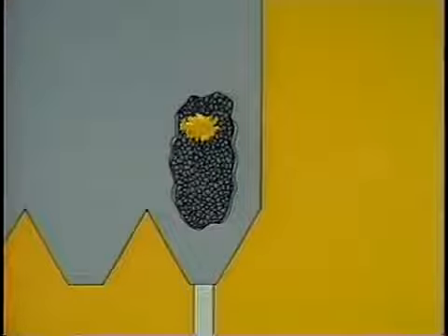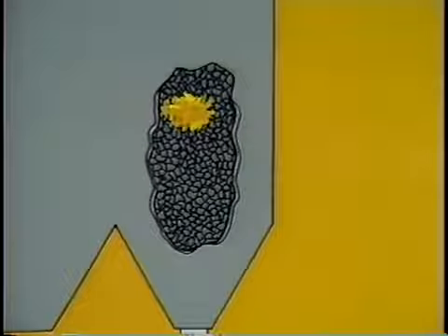Let's look at bunker fires first. Bunker fires can be caused by an existing fire in a coal pile being transferred to the bunker when coal is moved to the plant. Bunkers can also catch fire due to spontaneous combustion. An operator can often detect a bunker fire by the smell of burning coal, or in some cases by smoke rising out of the burning area of the bunker.